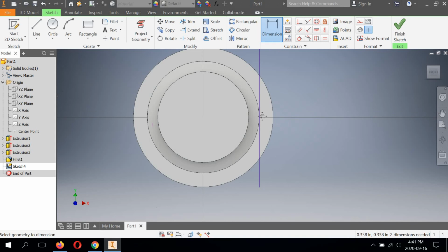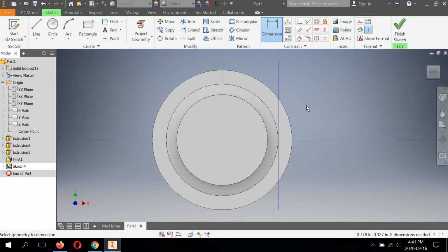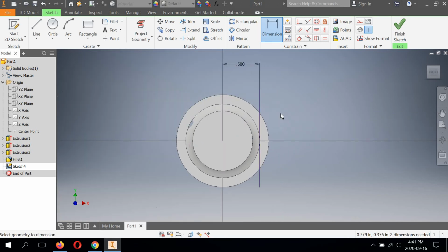So that constrains it. I don't know if you've noticed, but every time we constrain a piece of 2D sketch geometry, it goes purple when it's constrained. When I originally drew the circles, they were green. And as soon as I applied a constraint to the diameter, I was getting them to turn purple. So you really need to make sure things are constrained in the software. You really shouldn't be extruding anything until the line geometry or circle geometry or whatever it is you're sketching turns purple.